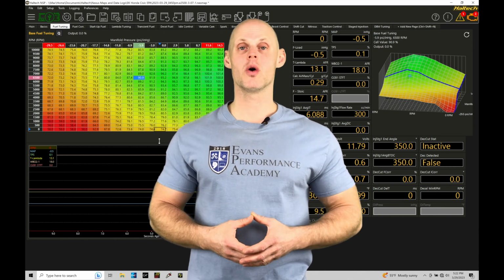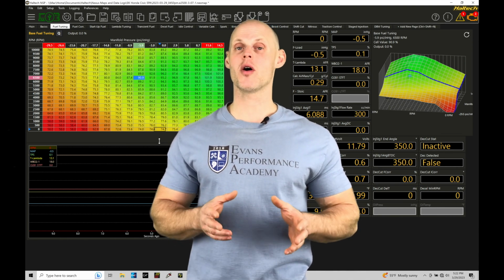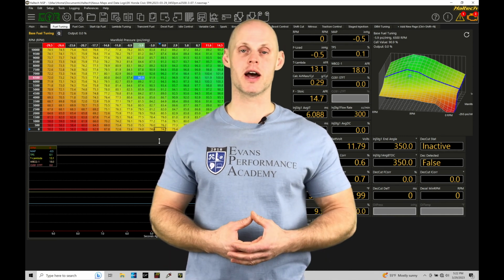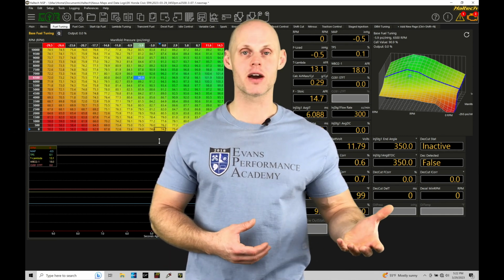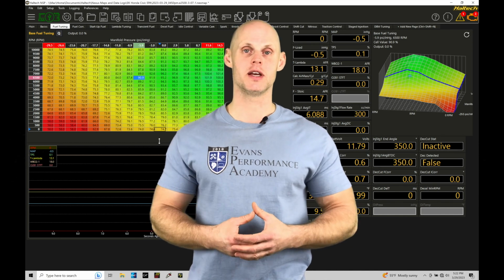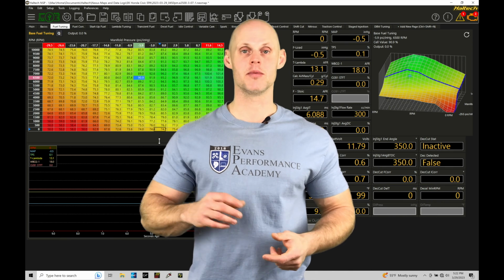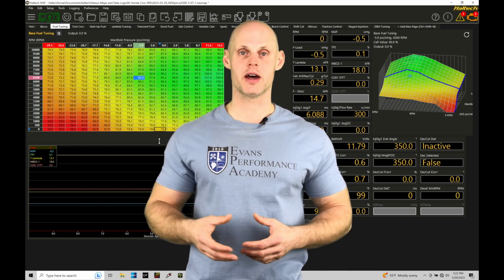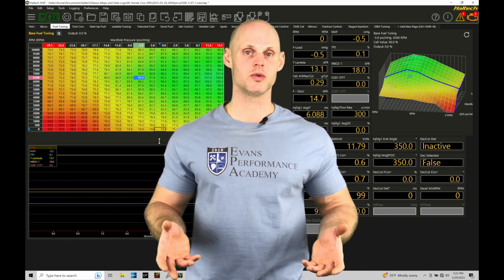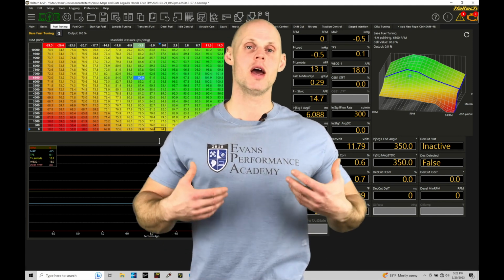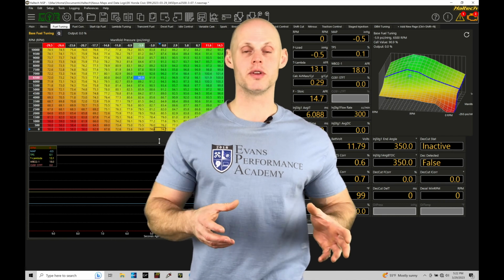This training tutorial, we're going to be taking a look at how to program our variable cam control. So depending on what type of engine you're dealing with, you might have an Evo 9 with MIVEC, which is the variable cam on our intake cam, a Honda K-Series that has the VTC, or variable cam timing, on our intake gear. You might have a Subaru EJ25 engine with dual AVCS, which is the Subaru language for variable cam. We have to know how to control this within the software.